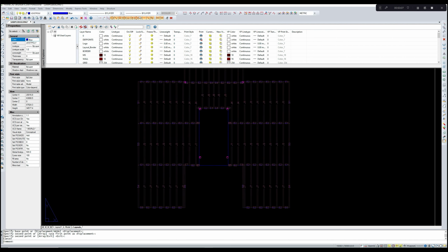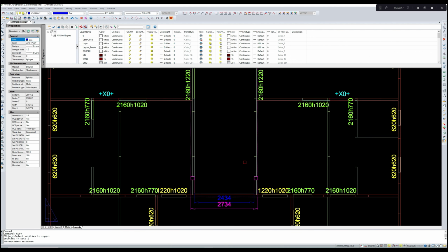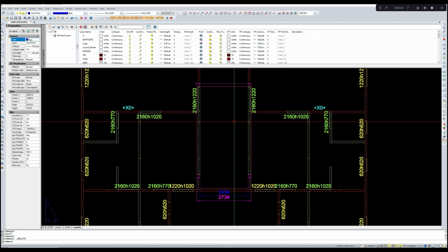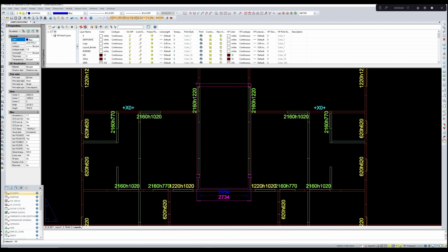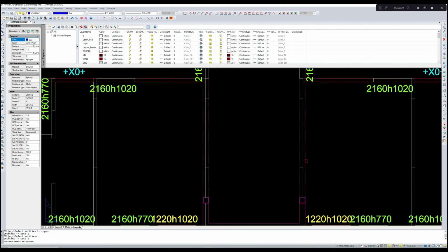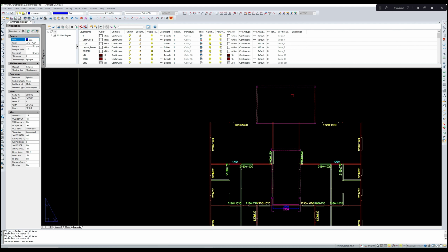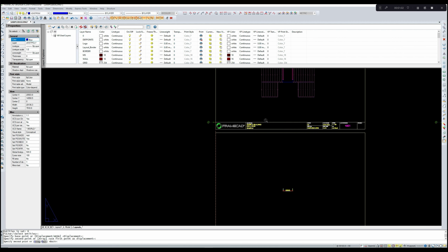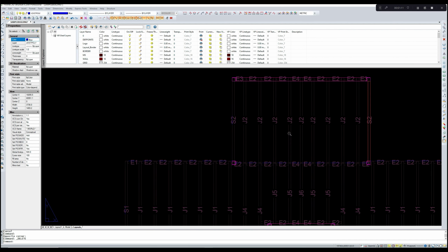We can copy the beams as well. Let us copy them as well. So you copy this beam, CO copy on the command bar, this beam, this beam, this beam, this beam, this beam, this beam, enter, select the base point, paste it here. So we really do not need this to be shown here, this beam and this beam, because there is a joist over it.